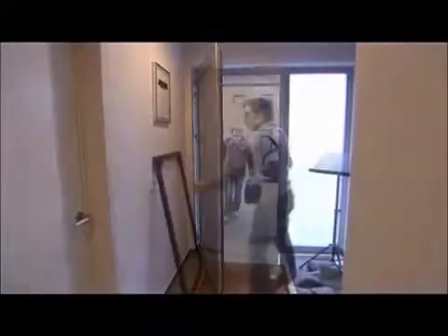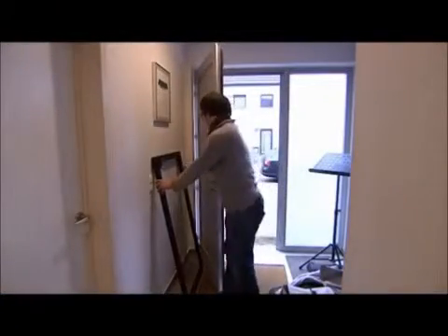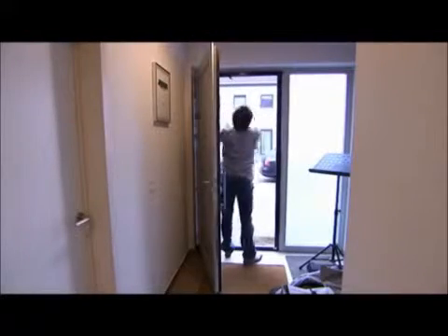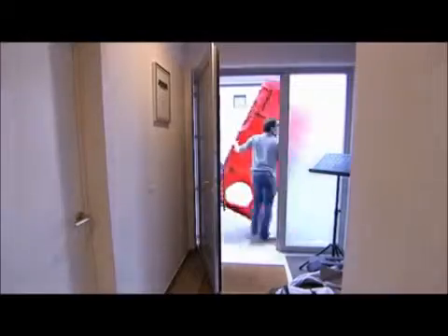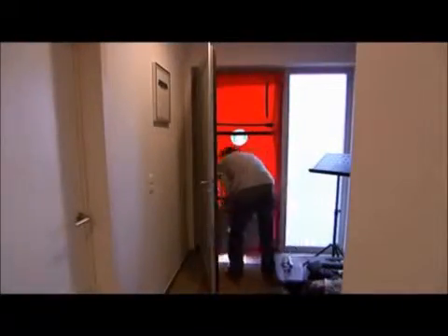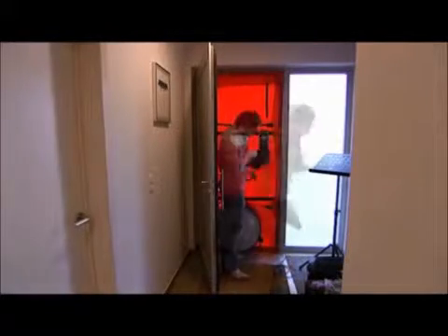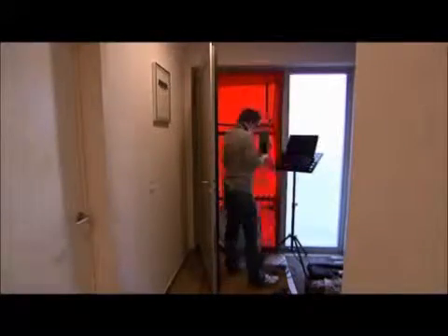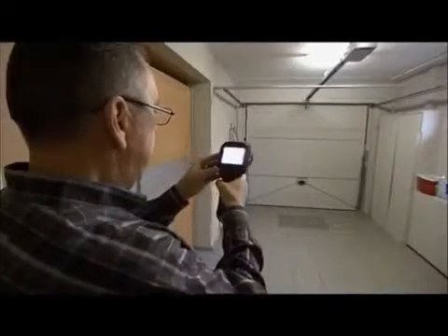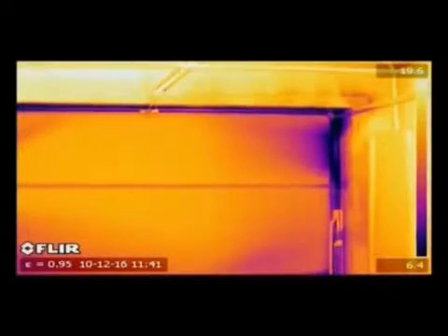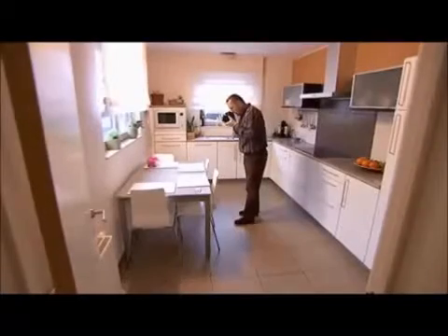Thermal imaging can also be used inside buildings. Air leaks in buildings can be visualized by identifying the air change rate with the help of what's known as the blower door process. This process creates underpressure in the building. Since the air pressure outside the building is higher than the pressure inside, air will try to enter through unsealed areas. Air leaks can easily be visualized with a thermal imaging camera. Thanks to thermal imaging, there's no need to fill the room with smoke to visualize the airflow.